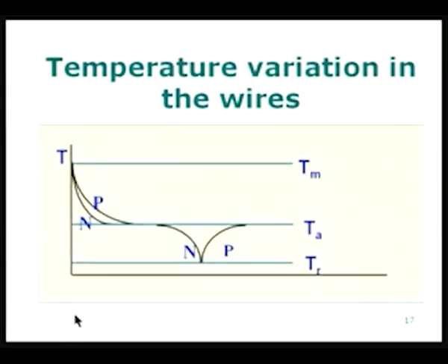Normally what is done in practice is to take, from very close to the junction, maybe a few centimeters or maybe a few tens of centimeters of the thermocouple wire, and from there onwards we can use a lead wire which need not be the thermocouple wire, which is usually very expensive.